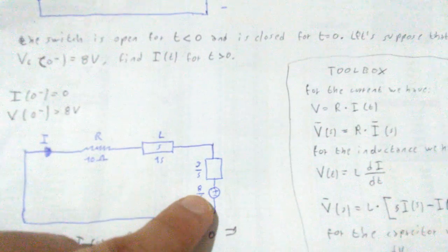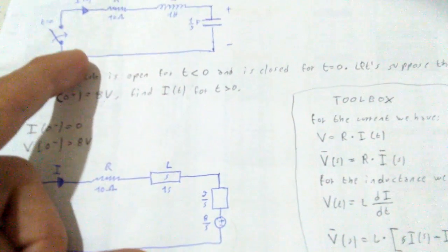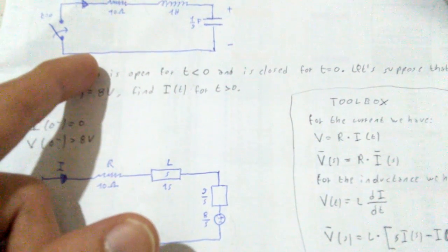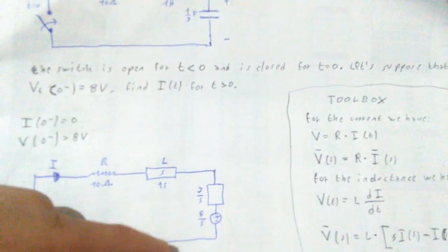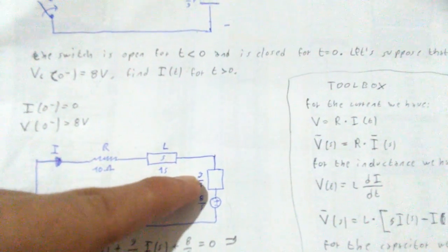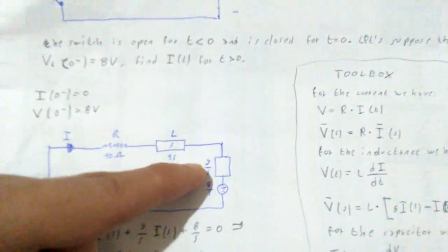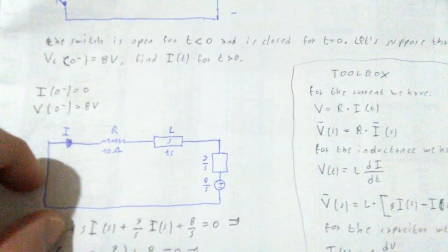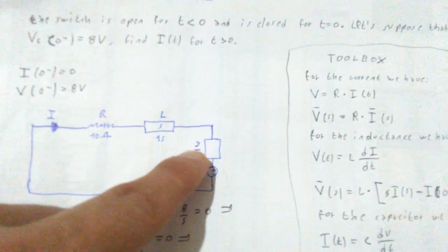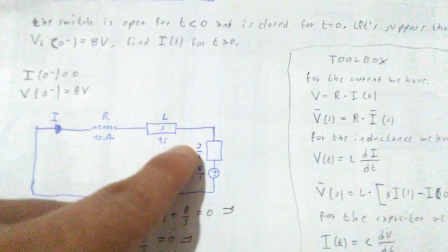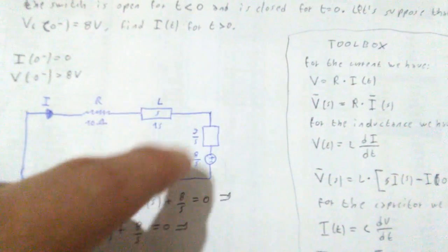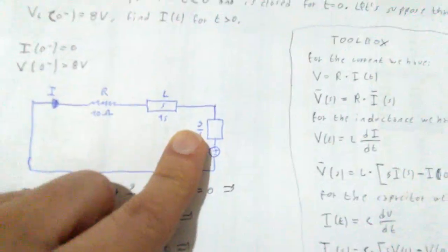Please note that this is only because in this very example, the capacitor is charged, there is no other power supply, and the switch is closed. If it was just a normal capacitor with an existing power source, and therefore it was not charged, was discharged, then we wouldn't have written it this way. We would then just write the resistance. It depends.